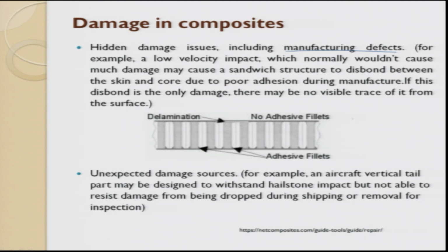In order to explain a little bit more, what are sandwich structures? Sandwich structures are structures wherein you have a softer core. This is called the core and this is called the skin. It follows the analogy of your I-beam. Here the skin can be made out of glass fiber, carbon fiber or Kevlar, and they are just stuck on top of the core.